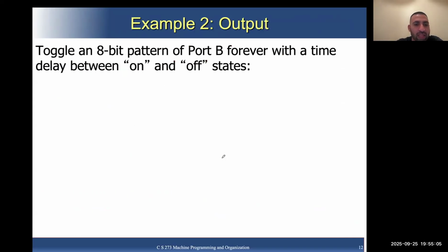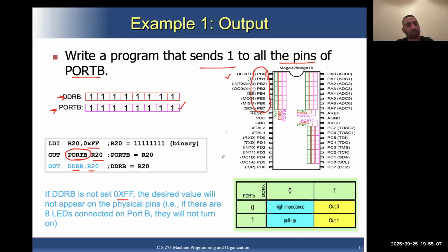Actually, when I was preparing lab 3, I was making this mistake of not setting the DDRB register. Actually, I was setting it, but the execution control from the C or from the .inf file was entering the assembly file at a point before where I was setting the DDRB.